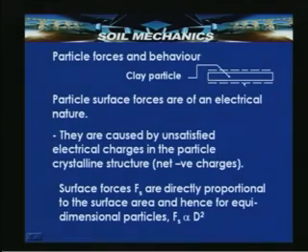If you consider in this slide, a clay particle is shown here. Clay particle is predominantly represented as a platelet shaped particle, with the surface shown as negatively charged. Particle surface forces are often electrical in nature, and they are caused by unsatisfied electrical charges in the particle crystalline structure. That is, there will always be net negative charges on both sides of the surface of the clay particle. So, surface forces Fs are directly proportional to the surface area, and hence for equidimensional particles Fs is proportional to the square of the particle size.